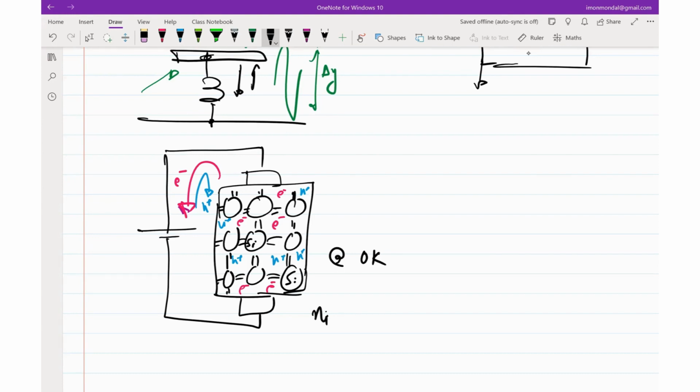But then if we take this same piece of pure silicon and we dope it with an impurity, and not any kind of impurity, let's say an impurity which has 5 electrons in its outer orbit, for example arsenic or phosphorus, then we basically dump those atoms into this piece of silicon. So what's going to happen? Some of them are going to replace some of these silicon atoms. I mean, not all, but some of them are going to replace a silicon atom.